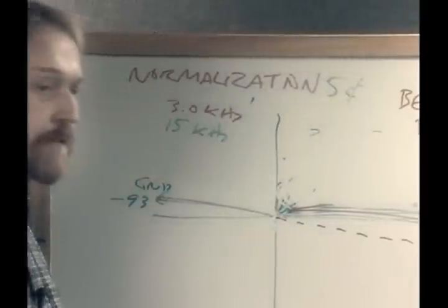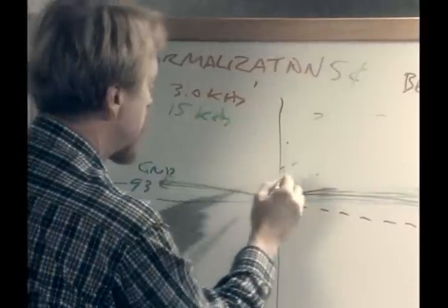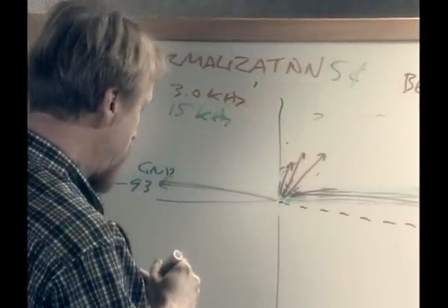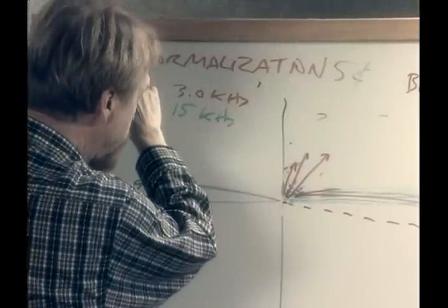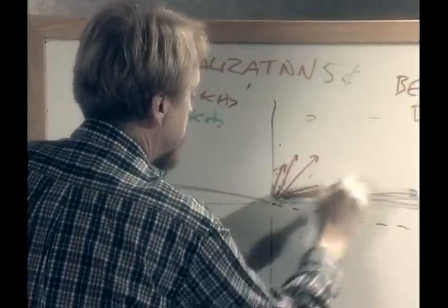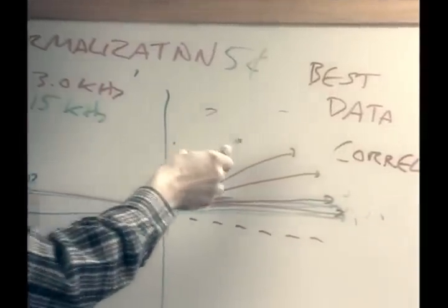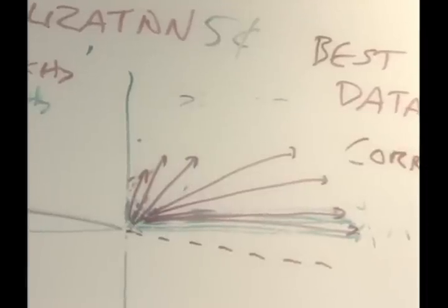As I mentioned earlier, for example, at 3 kilohertz, targets tend to crowd together in this neighborhood. And if you turn the normalization off, you can see at the other end of the scale, the targets in the silver coin and copper coin range will spread out nicely, and you can see that a lot better if normalization is turned off.